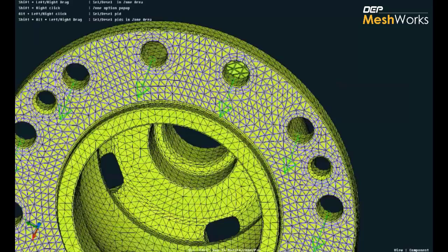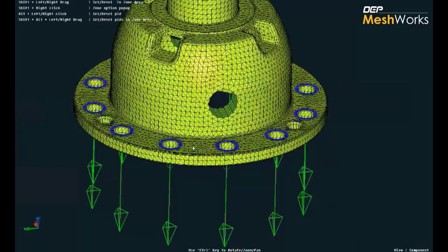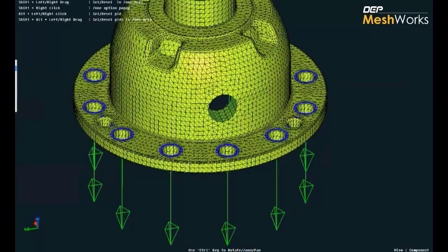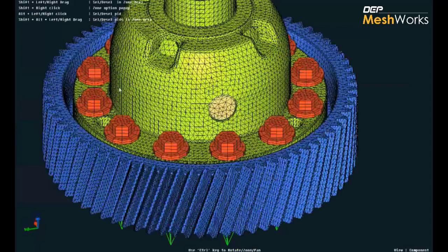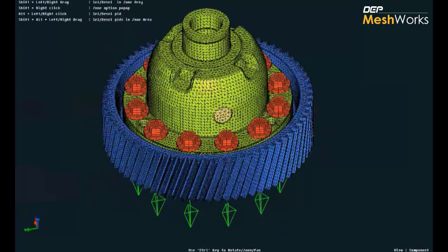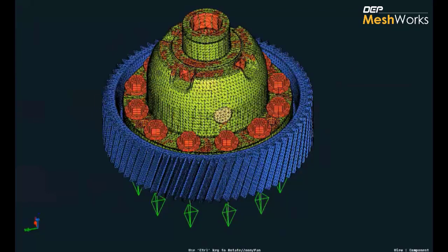Now when we do a part swap with an even coarser mesh, the contacts and surfaces, the bolts, everything should be updated automatically. So that is one scenario of the integrated modeler. Here, let me select all the models and go directly into the integrated modeler. In this case, I'm going to generate an Abaqus model. This is not a model conversion. It's a part swap scenario.